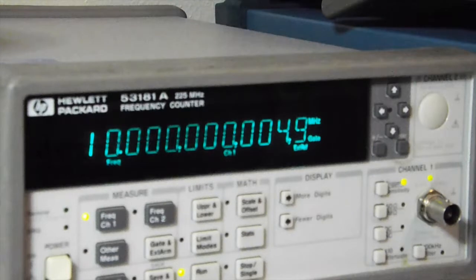For the following demonstration, the precision of our frequency counter is within 1 part in 10 to the 11th for a 10 MHz signal. Let it be noted that the 2975AR's blue waveform is indeed accurate to within 1 part in 10 to the 11th. Our best attempt at dialing in the 409B to within 1 part in 10 to the 11th came to within 49 parts in 10 to the 11th as a 10 MHz waveform.